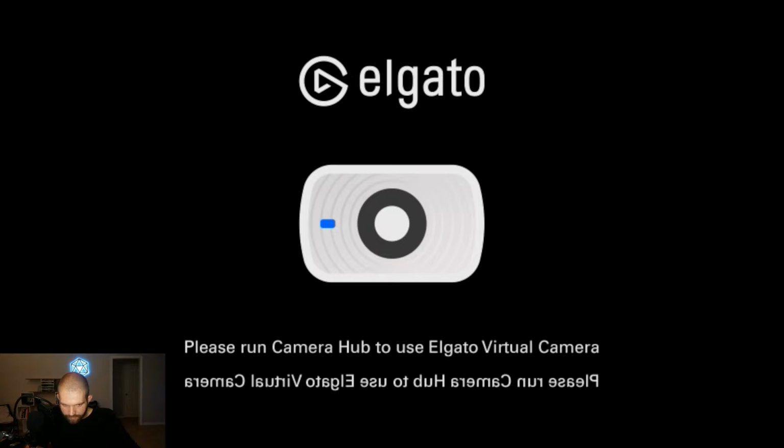Hit tab, select the faces I want to apply this to. I'll go back to my camera view so that it matches. It'll always use the view that you have in order to generate that AI image that it's going to project onto these geometries. Okay. So we see there we're getting some more interesting results. Now that I modified the UV for these two, it seems like they're too zoomed in, but that's fine. At the time being, I'll leave it as it is.